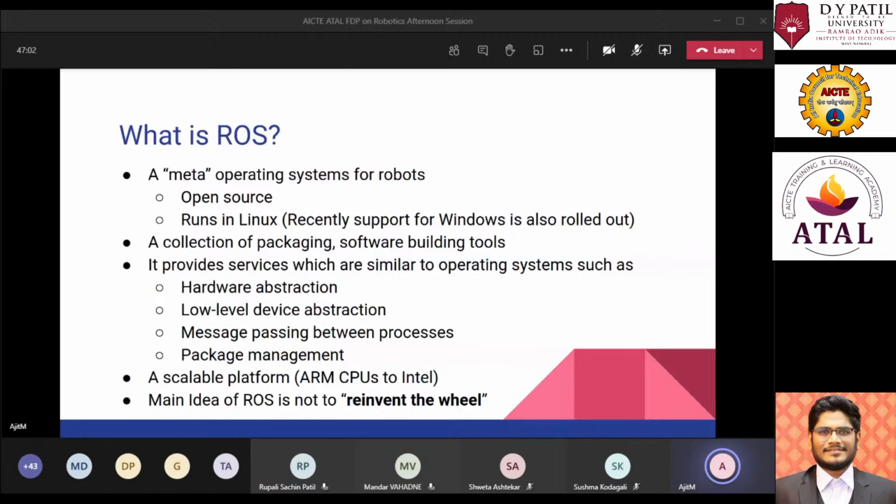Now this message over here is not a timestamp message, and sometimes there is a requirement. Actually, to be frank, most of the time there is a requirement of timestamp messages in robotics, because we need to keep up with the incoming data with the time, so you can take decisions according to that. So for that, they have defined a pose message which is stamped.